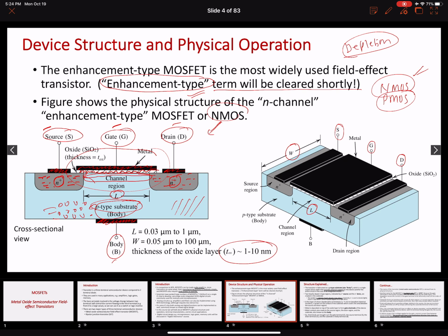For example, your device, this is just one transistor, right? The device can be a pretty big device. Let's suppose this is a big region in which we can have multiple transistors. It houses 3 transistors, for example, over here, right? With a common body or a common substrate. So what usually happens, and this is probably coming back to the body again, is that we can connect the body of this entire substrate to a specific voltage to create a normally off condition.